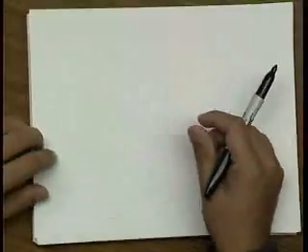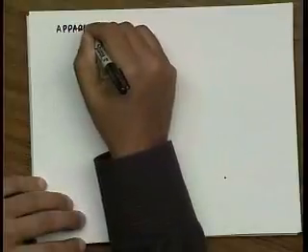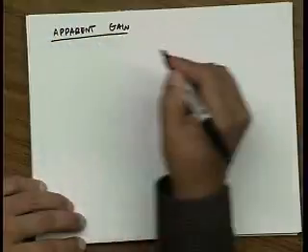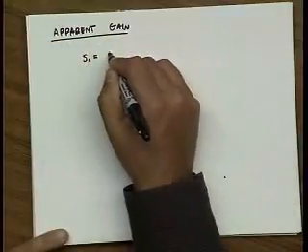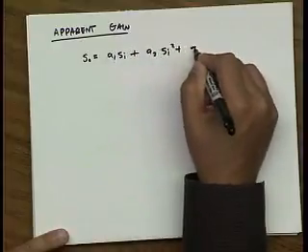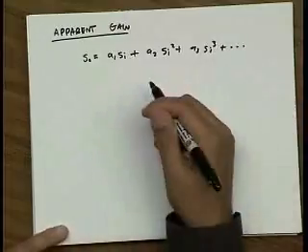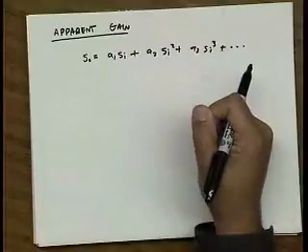All right, so let's calculate the apparent gain based on the small signal analysis that we did. So remember, we assume that we can do a Taylor series expansion on the nonlinearity, and let's say that the cubic term is sufficient to understand the behavior of the system.